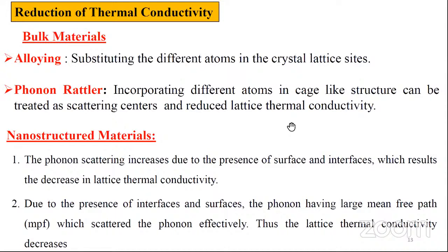So which can scatter the phonon more. The more the scattering, the lattice thermal conductivity will decrease. So from our discussion, we come to know that the heavily doped semiconductor is the best thermoelectric material.